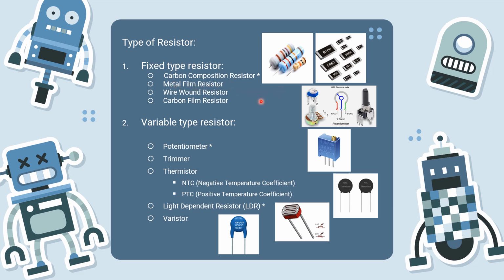In general we have two different packages of electronic components. We call them SMD or sometimes SMT, and DIP. DIP means dual inline package, and SMD means surface mount device or technology. This is the SMD one. SMT or SMD, it's the same, there's no difference.